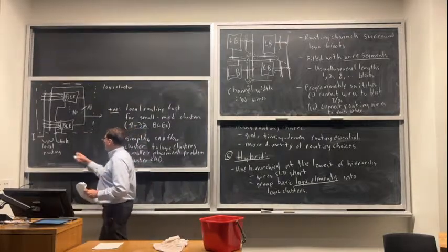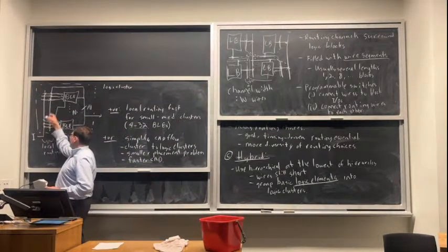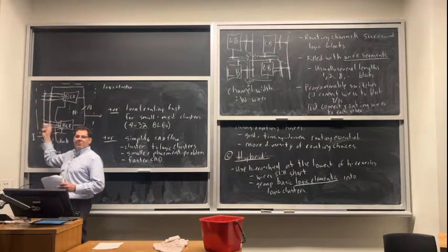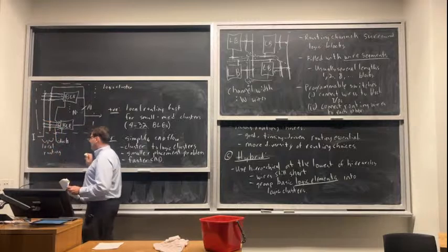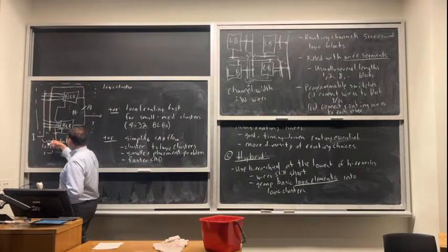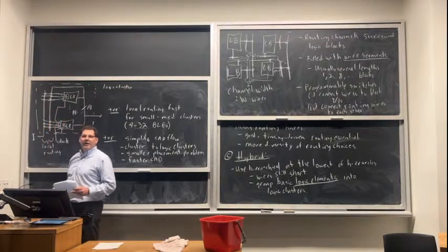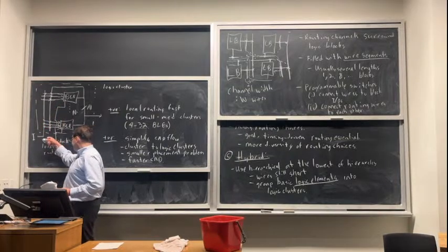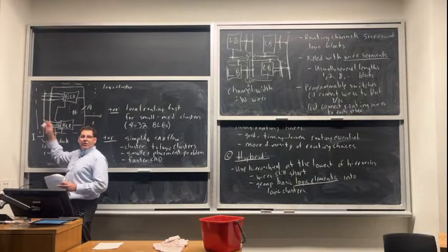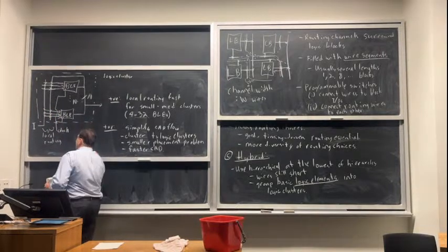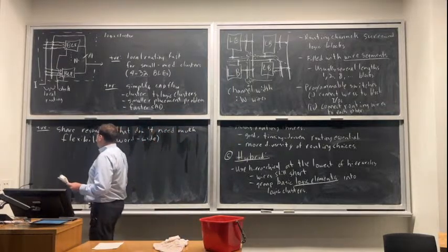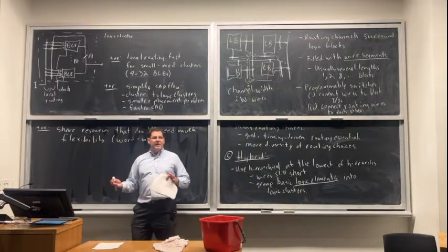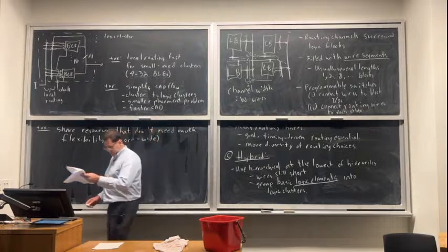Because you notice on this clock, I don't have these programmable switches. These programmable switches represent multiplexers. They cost area. And I didn't put any here. I just brought the clock in once. I didn't bring in 10 signals from the island-style routing. I brought one in, and I didn't put a lot of switching on it. I just hooked it up to everything. So that saves me area. And as long as that matches what circuits need, it's a good choice.